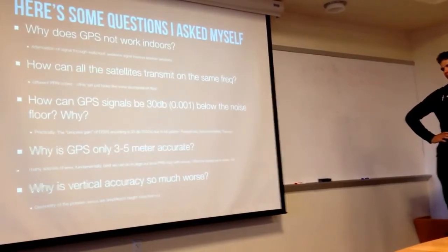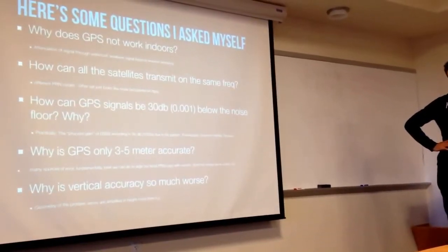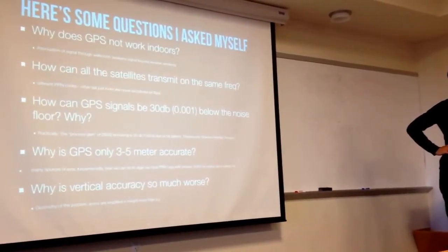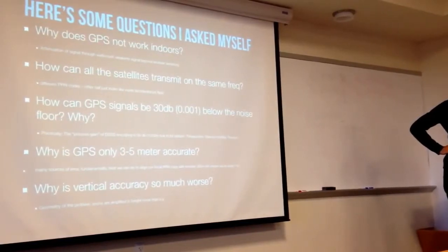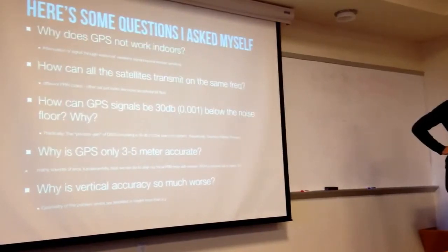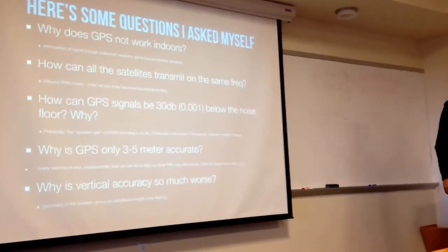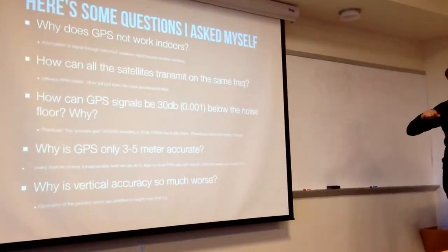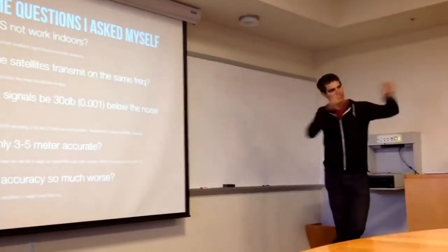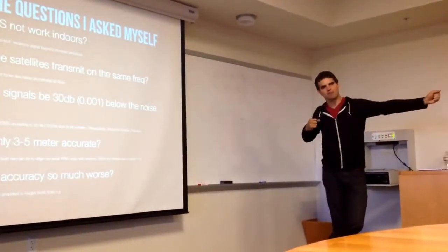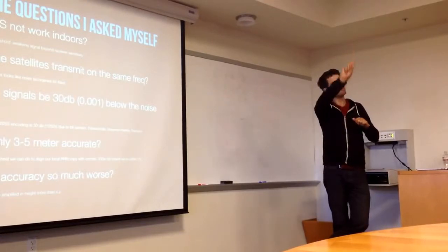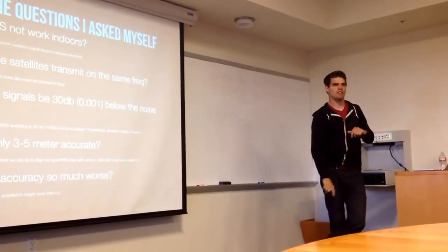Why is GPS relatively inaccurate? This is kind of cute, actually. If you think about those PRN codes that get sent down, these individual chirps, if it's running at about 1 megahertz, which it is, that means a single bit, if you stretch it out, is about 300 meters long. Right now, beaming down from these satellites, there are these 300-meter long ones and zeros coming down.